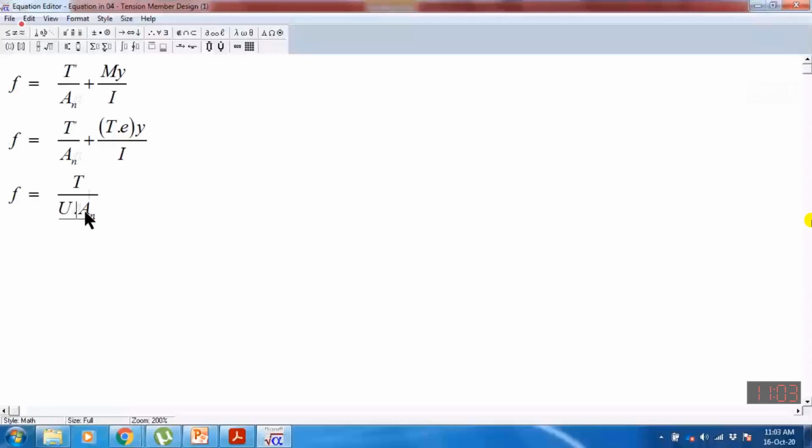So I am considering these bending stresses indirectly by reducing the net area. So I am assuming that due to the extra moment which is produced due to the eccentricity between the two connecting members, the section with the gusset plate, the area is reduced. So this can be considered as T over A_n.